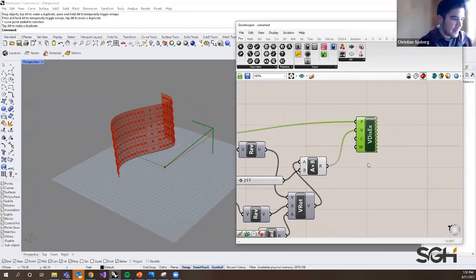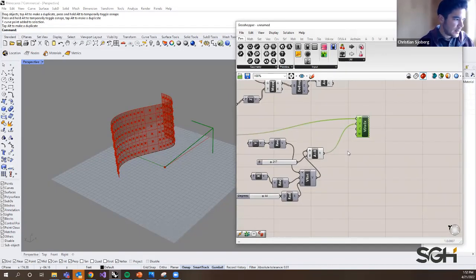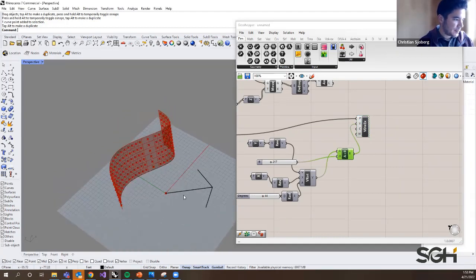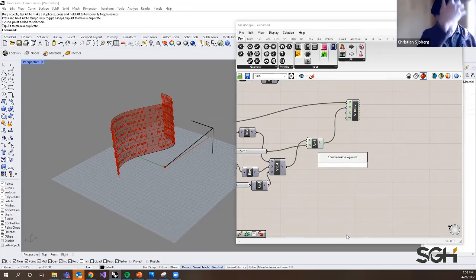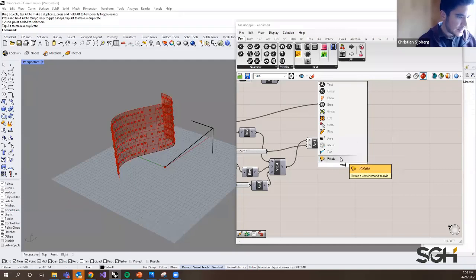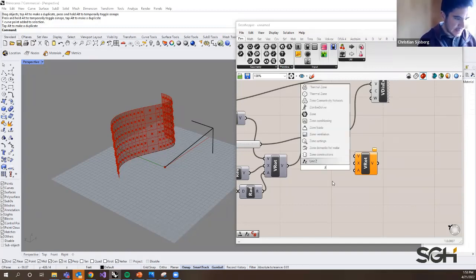All right, and then the next thing we're going to do is we also want to be able to rotate that vector along the azimuth. So this is the altitude. We want the azimuth, so we want to be able to say the sun rises in the east, sets in the west, so to speak. So let's do another little piece of vector math, another vector rotate, and that vector rotate is going to this time be rotating about the z-axis, right?